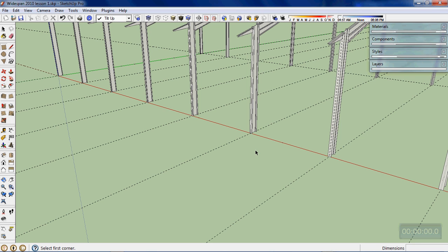You won't be able to see that by eye, and in fact if I even dimensioned the 149.8 millimeters, if I set the rounding of the dimensions to the nearest millimeter, it'd still dimension to 150 millimeters also. The difference is there'll be a tiny gap there which would enable me to triple click on the concrete tilt-up panel to select it in its entirety without selecting other elements that it might be joining. So with that in mind, my current layer is tilt-up, and I'm in the rectangle tool.